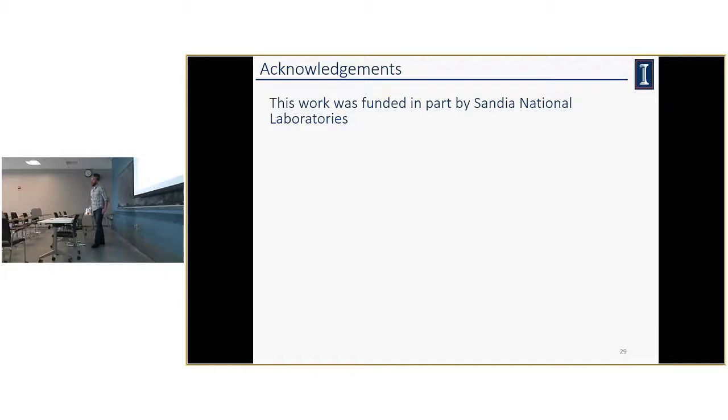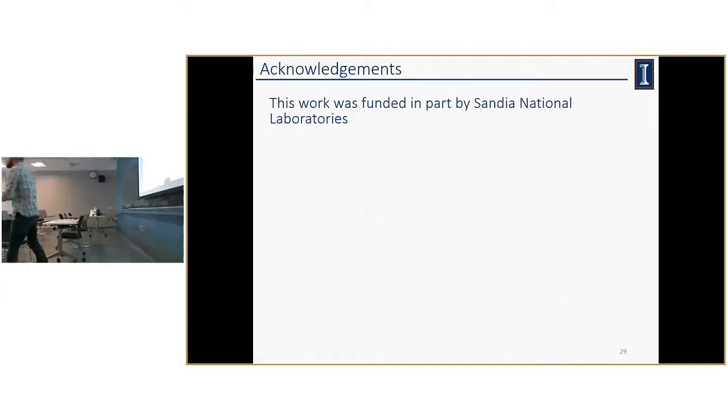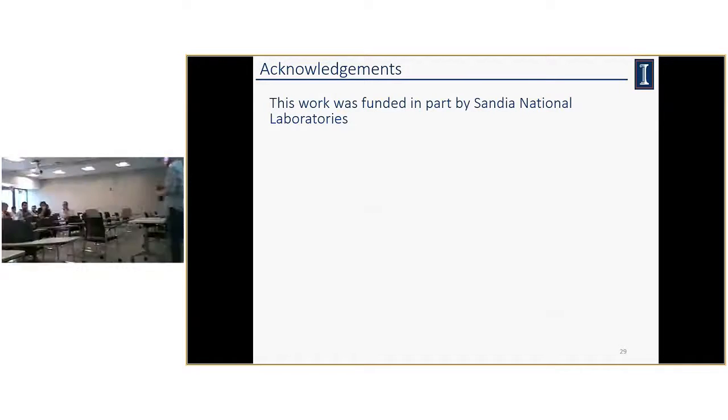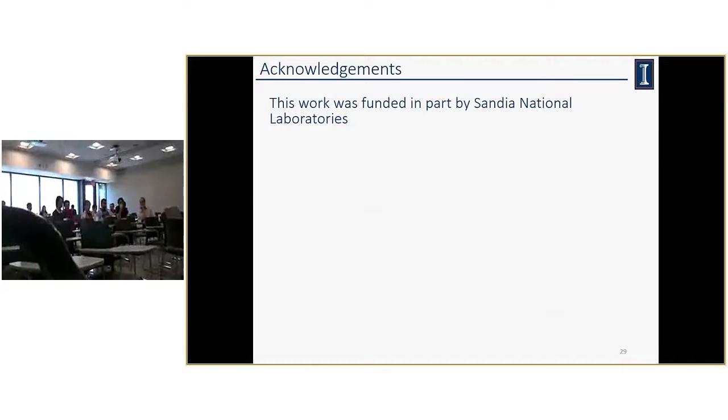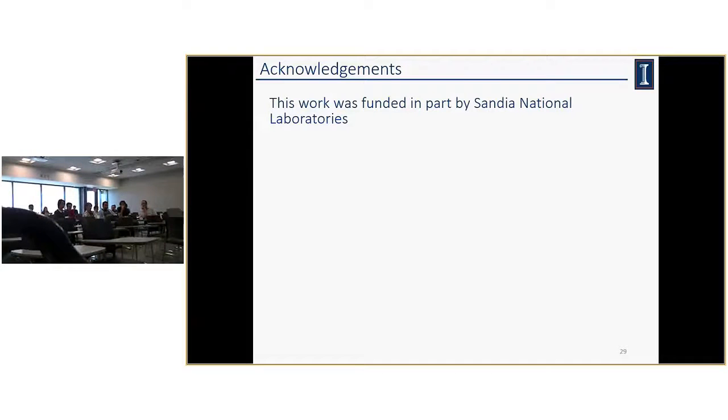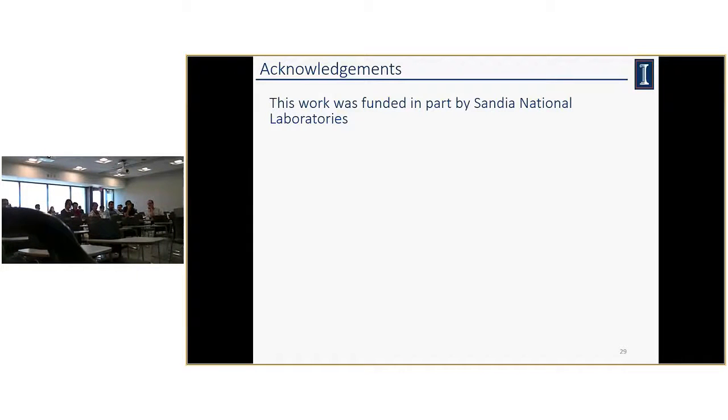Sure. Thank you for the presentation. On your slide showing the different duty cycles, whenever you're doing active balancing, it looked like there might be higher ringing on the cycle where you're regulating the duty cycle, or where you're maybe supplying power to the auxiliary supply. Is that something you noticed?